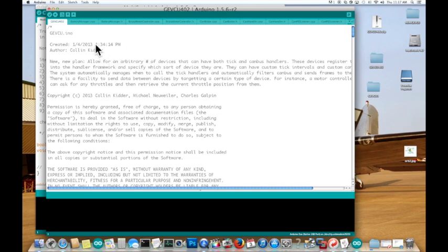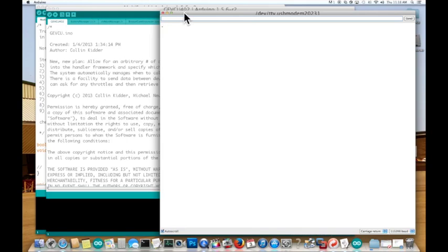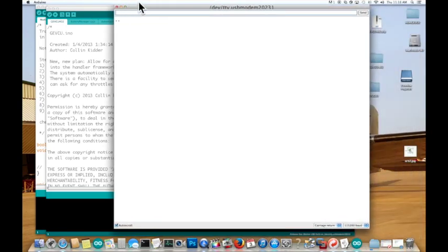And so that's kind of the thing. I told you that there was a serial terminal program in the Arduino. I mean, it's not really to compile anything or deal with software. They call it a serial monitor, and it simply brings up a serial screen. We want to set that to 115,200 baud, which is not precisely correct, but that's what they call it. And you can pick any of the various ones.